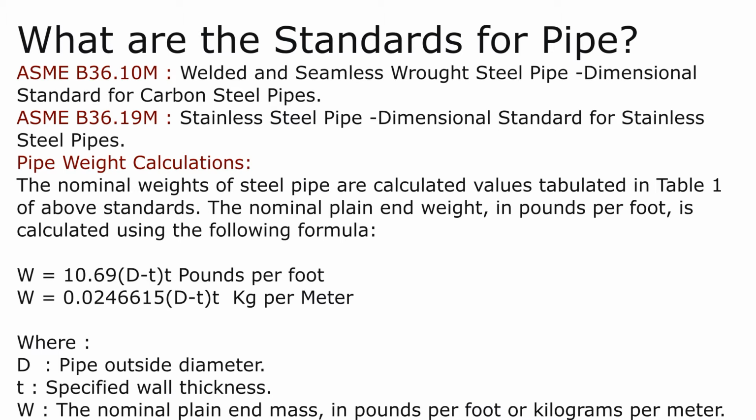And here you will find the suffix S is added to differentiate the thicknesses between B36.10 and B36.19. S, you can just remember, S belongs to stainless steel. So wherever the schedule is written like 5S, 10S, 40S, it means it belongs to stainless steel pipe.